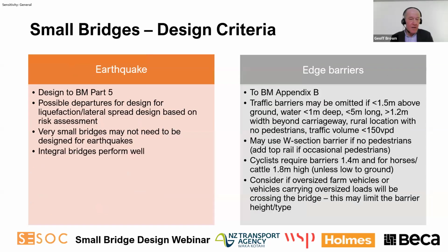Earthquake loading. Design is normally to Bridge Manual Part 5, but it is possible to get departures for design for liquefaction, lateral spreading design based on risk assessment. Very small bridges may not need to be designed for earthquakes.